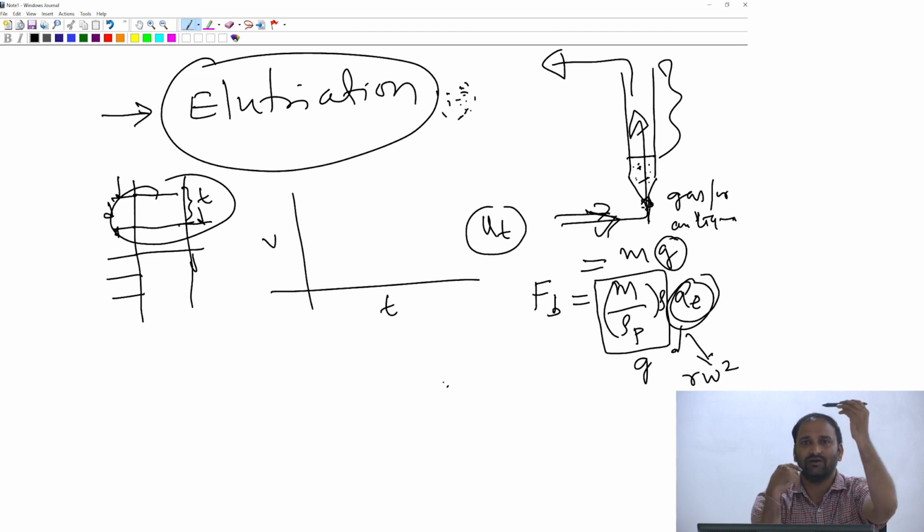Everyone agrees, right? If I have a cylinder which is falling, the area that is perpendicular to its flow is going to be the rectangle, your length times the diameter. However, if it's falling with its axis in the direction of the external force, your projected area is going to be the same as the sphere, pi r square. It basically sees a circle, right? So you should be able to develop these equations for particles of other arbitrary shapes and work out the settling velocity expression.